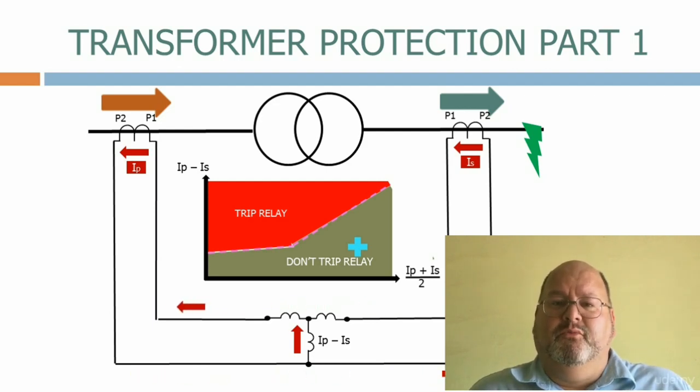Transformers feed power into the network from the generating stations, and therefore also feed the network with the high currents that occur when a fault happens on the network. If transformer differential biasing wasn't used, all of the currents that pass through the transformer on the way to the fault on the network would destabilize the transformer differential protection and trick it into believing that the fault was actually on the transformer. The slope and pickup values of the biasing curve can be set very precisely, making it very easy to identify whether the fault is on the transformer or not, without adding too much additional time delay.